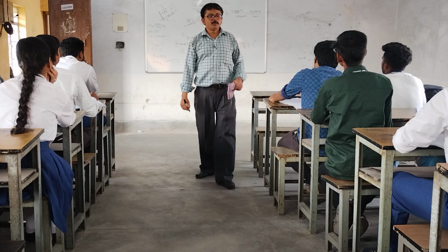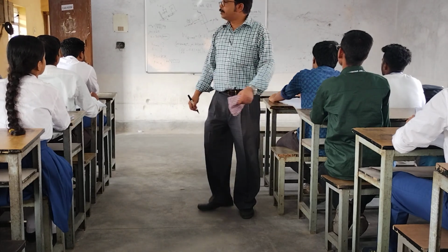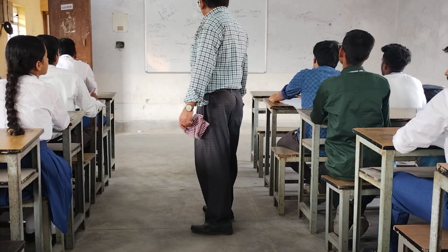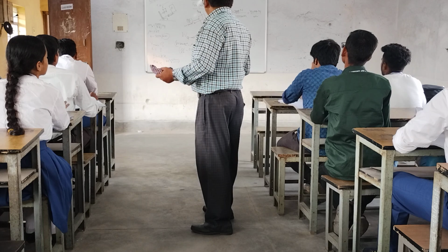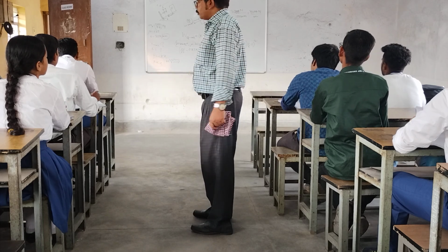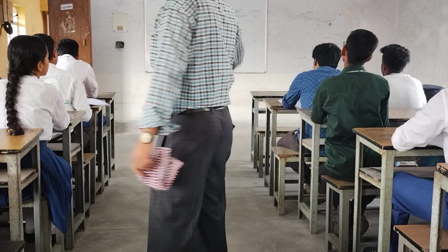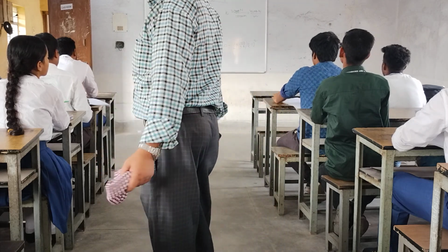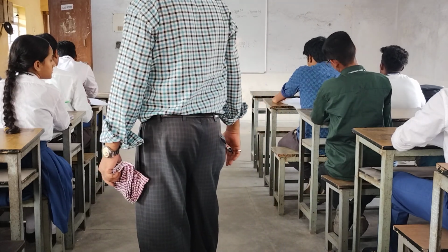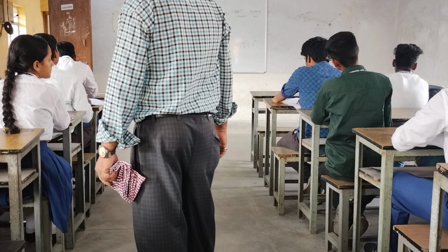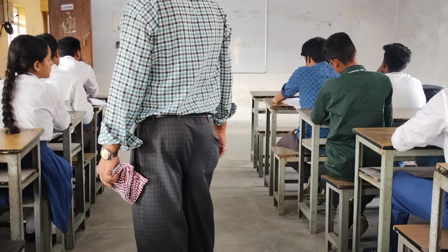Here in the numerator 30 newton, in the denominator 1 millimeter. You want to change 1 millimeter to 1 meter, so you multiply the denominator by 1000. If you multiply the denominator by 1000, you have to multiply the numerator by 1000. So you put the value of k as 30,000.